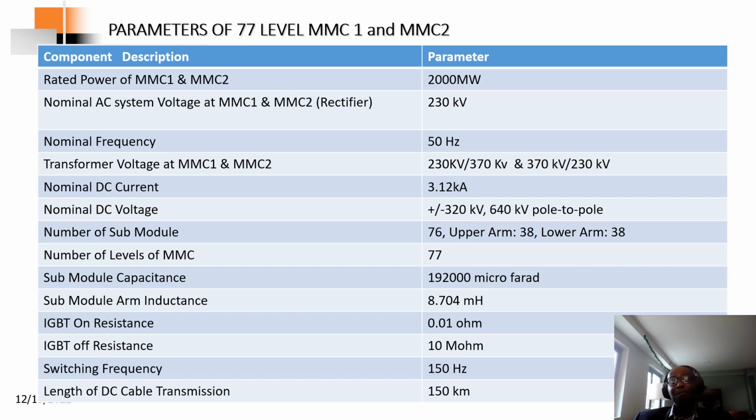Remember, the converter on the offshore side, I have an AC bus of 230 kV. I step it up through a transmission level export transformer, and that steps the voltage from 230 kV to 370 kV. The goal is to achieve a 370 kV AC voltage level, which will produce the equivalent DC voltage that I need.